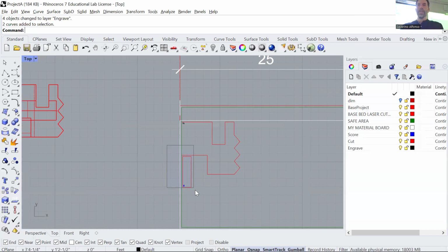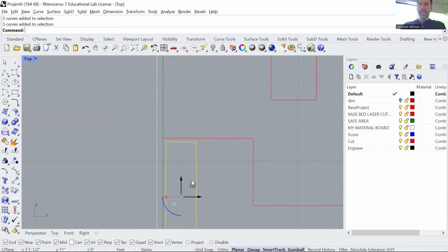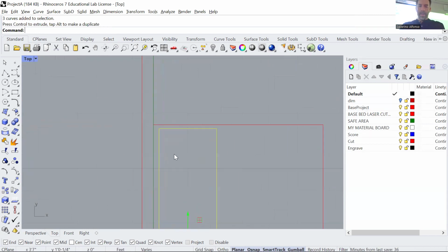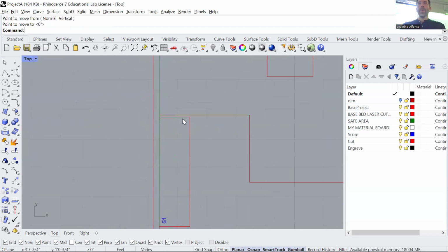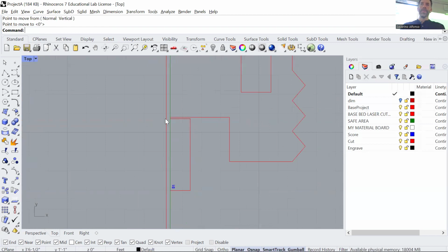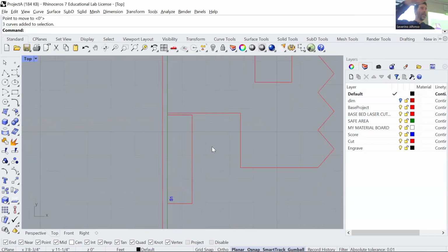And you go on. Notice that I am rotating some pieces and I'm not really touching because that's not a great idea, but you want to be within the safe zone and close to the neighbors, almost in a bit of a distance, because the laser burns through it.